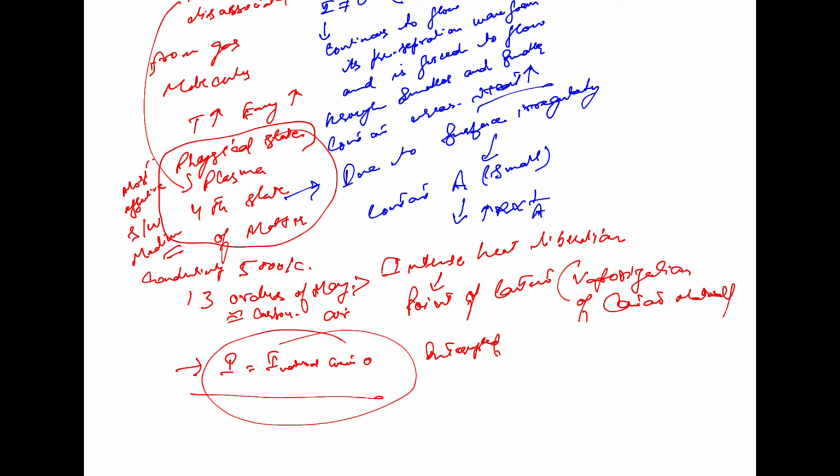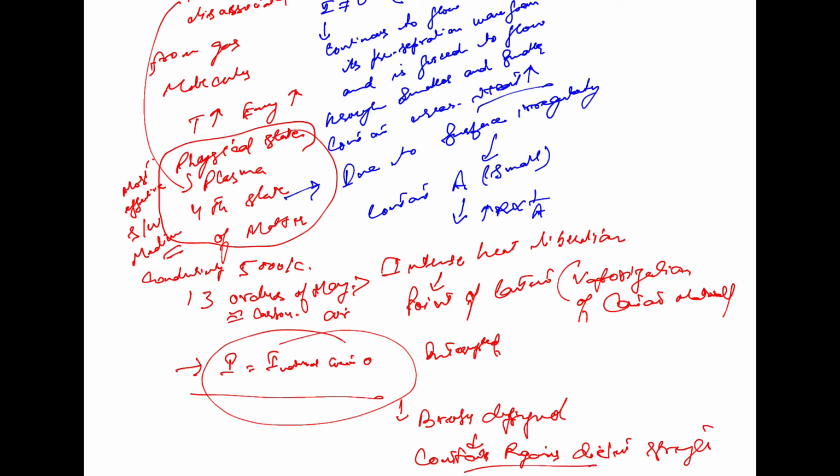The circuit breaker is so designed that contacts regain their dielectric strength as quickly as possible after the current zero, so that the arc does not restrike. However, this may not be possible at the very first current zero after the contact separation, as we have discussed in the graphs also.